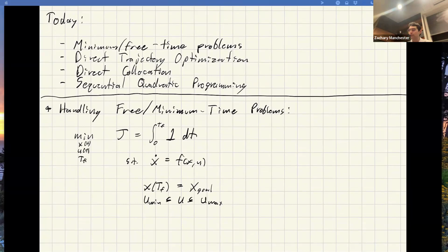So now with those input constraints and the goal constraint, the optimum for this in a lot of situations, not always, but in a lot of situations, is to basically slam the actuators full gas one way. And then when you're at the halfway point, it's full brake. And so you just land on the goal constraint. That's called a bang-bang solution. There's a little bit of theory on when that happens, but in a lot of cases, that's intuitively the answer for a lot of these things.